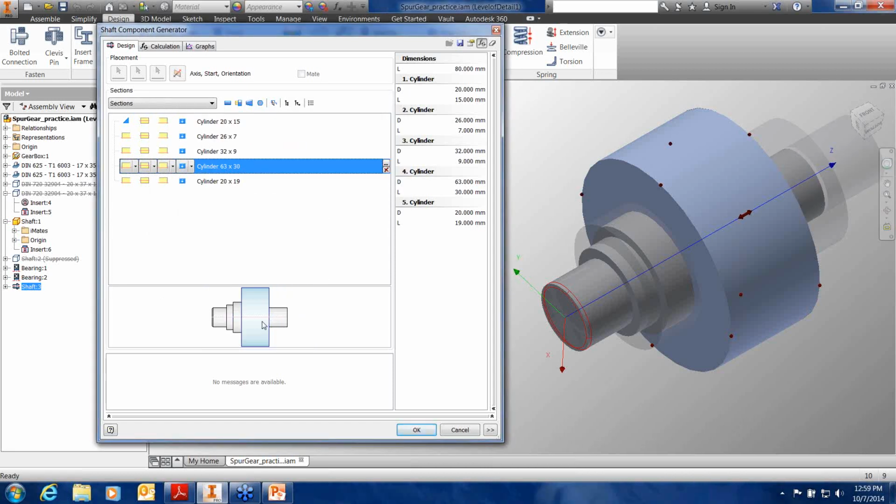You'll notice it's starting to update here down in the preview of our dialog box as well as over here in our model. Now there's also red dots over here. As I put my cursor on it, it says I can actually drag values as well, and they'll update in the dialog box. I can drag placement just by grabbing these arrows and the dot locations if I wanted to visually get something in place that I didn't know exactly what the value was yet. So there are free-floating sizing ways of putting the features in there, or more specific by doing it over here in the dialog box.